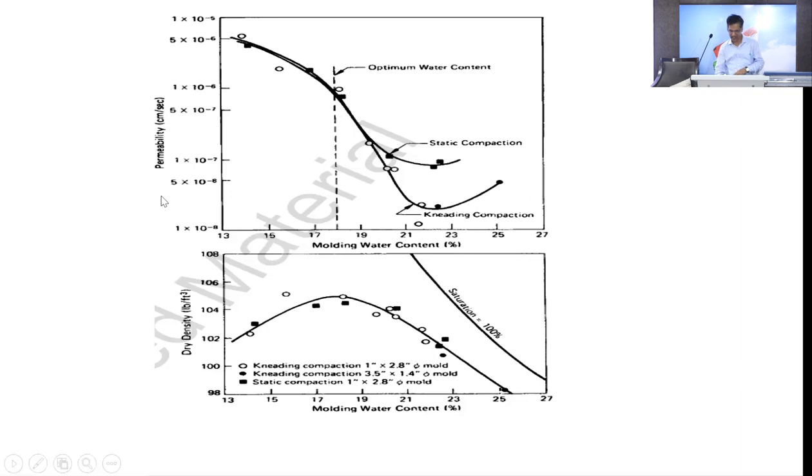So now you see, what do you want? You want an impermeable layer. When we don't have geosynthetics, geoliners and so on, we use only the soil itself as an impermeable layer. So if I am doing kneading action, it reduces permeability by a factor of, suppose, 2, but with static compaction, at maximum I can go up to 6 or so. So there are 2-3 times you can reduce the permeability if you go with the kneading action, because for permeability you have to go with fine grained soil.